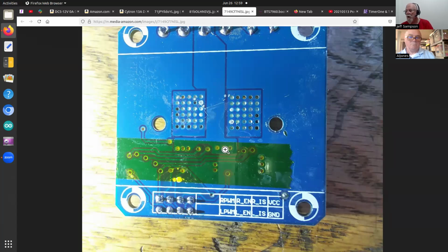So at one point, somebody said, well, put Kapton tape across these. And then somebody said put like a thermal pad across these, because this is where the heat comes through from the back. So you put a thermal pad, then put the heatsink back on, and they're claiming that's going to solve all your problems. Somebody's saying actually fill the holes with solder, but I haven't seen anywhere that anybody else says you need to do that.